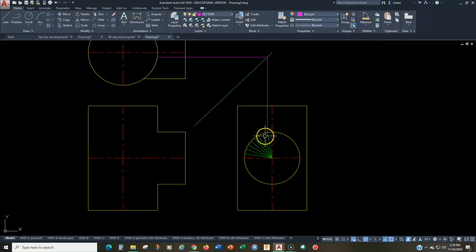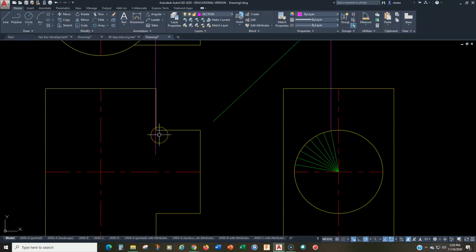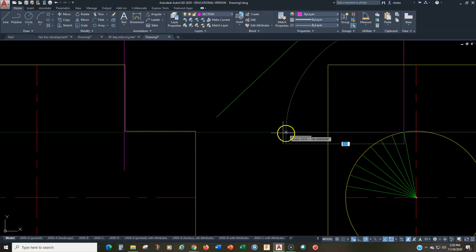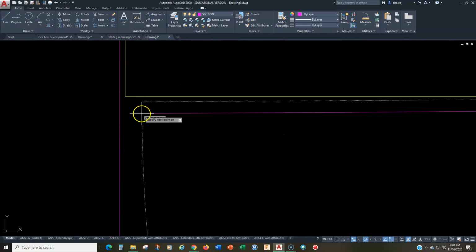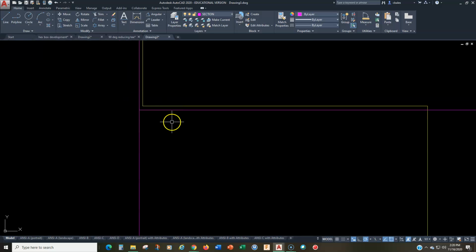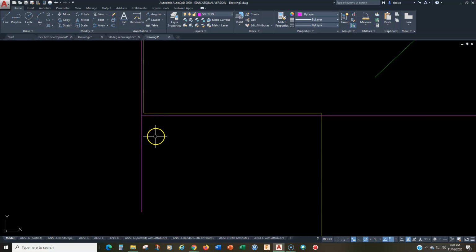All right, so now what do I do? I start here, I draw a line up, hit the miter line, come over, hit this line, and now I'm going to go straight down. How far? Well, I don't know, all right? I don't know, but I can find it by going and completing the curve. Now here you have to be careful. Notice how close this is to the yellow lines.